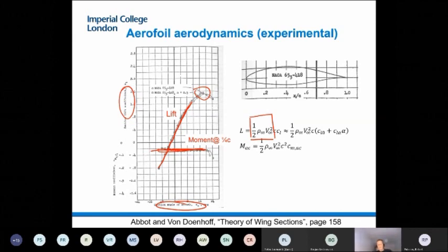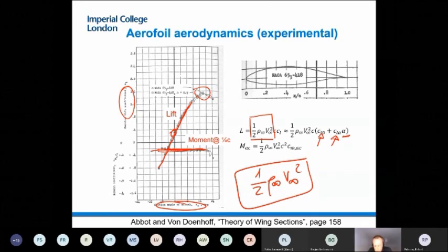So what we have is a very simple model for aerodynamic performance. First, all the aerodynamic forces scale with the dynamic pressure, a very, very important parameter. Anything that has to do with aerodynamics, it will appear in many equations today. The second is that the resultant lift coefficient, CL, goes linearly with the angle of attack plus a constant. I'm going to call them CL alpha and CL naught. CL naught is the value at 0, and CL alpha will be the slope. The moments are simply a constant, which again is measured for anything we are concerned about right now.